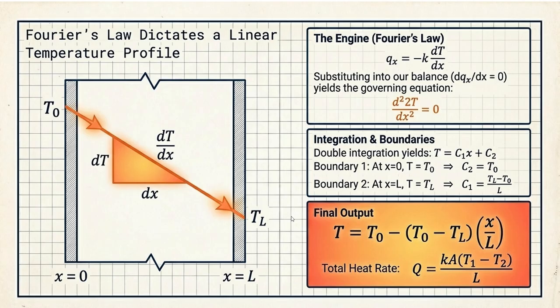That is our concentration profile that we can write across the slab's length. And if we want the total heat rate, so that was flux, basically qx is flux, heat supplied per unit area. So if we want total heat rate, we'll have to just multiply flux with area. So flux was k into T1 minus T2 by L. Just multiply it with area A, that is the surface area of the slab. So we'll get total heat rate Q equals kA into T1 minus T2 by L.